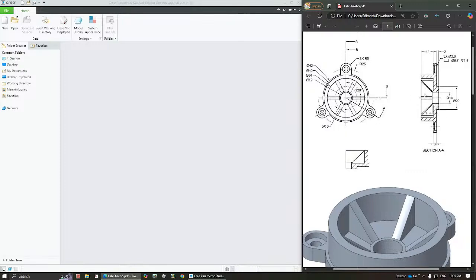But when we are drawing the sectional view, this section, which is actually inclined, will be made straight, and then its cross section will be drawn over here, so that when we see the sectional view, it should appear symmetric. But there is a disadvantage of this, and that is that we will not see the actual cross section of the object of revolution anywhere in this diagram, and that is the reason why a section BB has been created over here, and that section has been given over here.